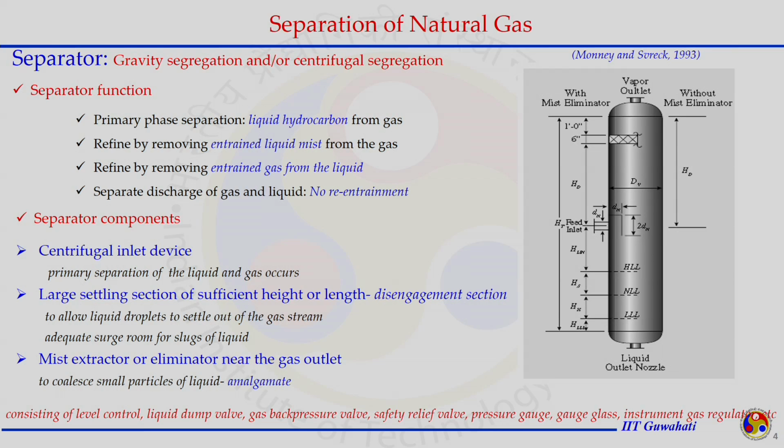Further, in the next step, the entrained gas within liquid, because the liquid is also carrying some amount of gas, either in solubility form or as free gas associated with the liquid. The separator design as well as operating condition should be in such a manner that the entrained gas is also getting recovered from the liquid.